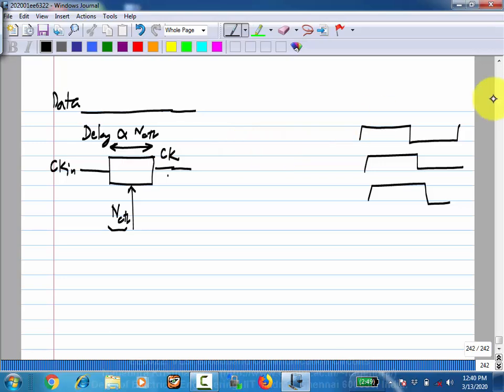And in this digital implementation, of course, the output of a linear phase detector is analog, right? The information is in the area of the up minus down. So it doesn't make much sense when you want to generate this digital control. You can do that, but you will need an analog to digital converter to convert that information. So we'll assume basically a bang bang or a digital phase detector here.